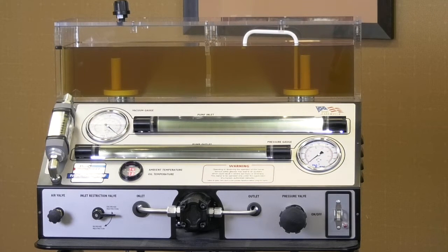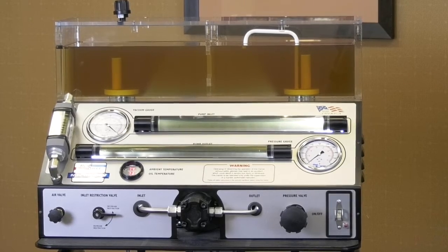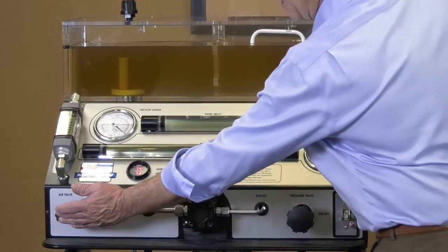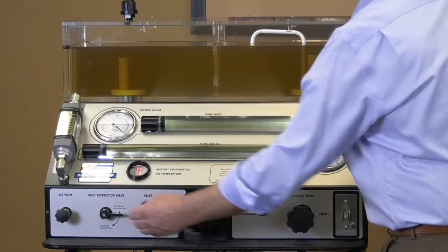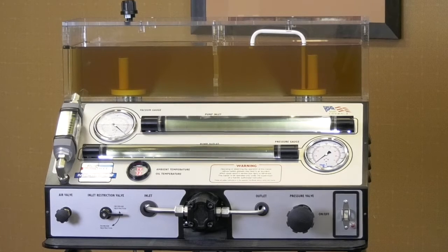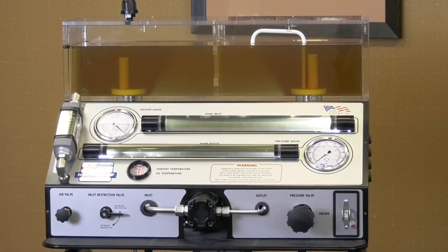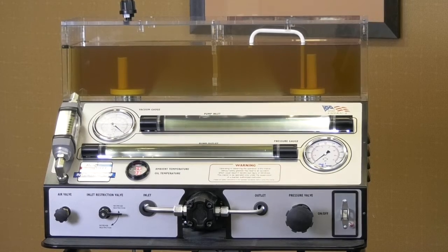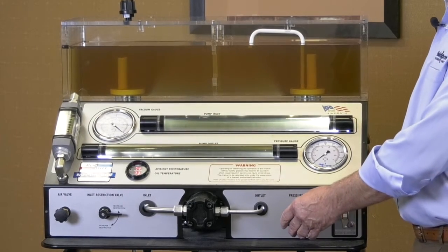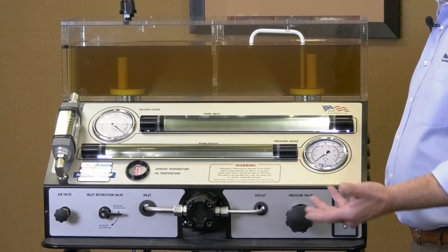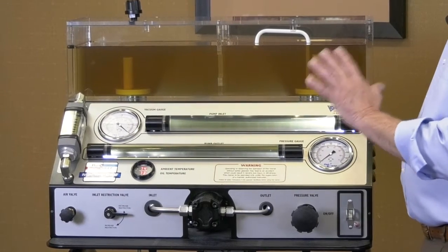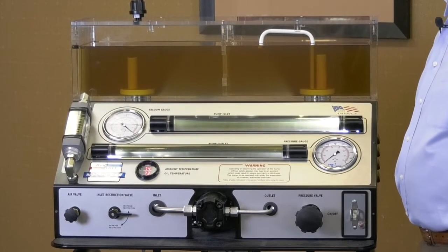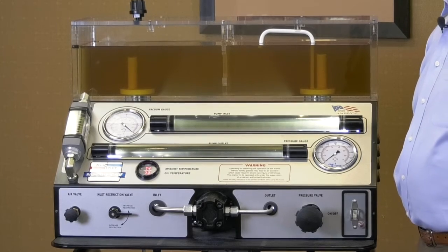In order to facilitate cavitation and pseudocavitation, or air contamination of the oil, we have a valve on the left-hand side of the trainer that will allow air to go into the intake of the pump. We have a valve here which will restrict the flow into the pump, so that can simulate a plugged screen, an overspeed condition on a pump, and so on. And then we have a valve here that we can use to generate resistance when we want to exacerbate the noise of cavitation. So we'll be using this trainer for demonstrating both cavitation and pseudocavitation.